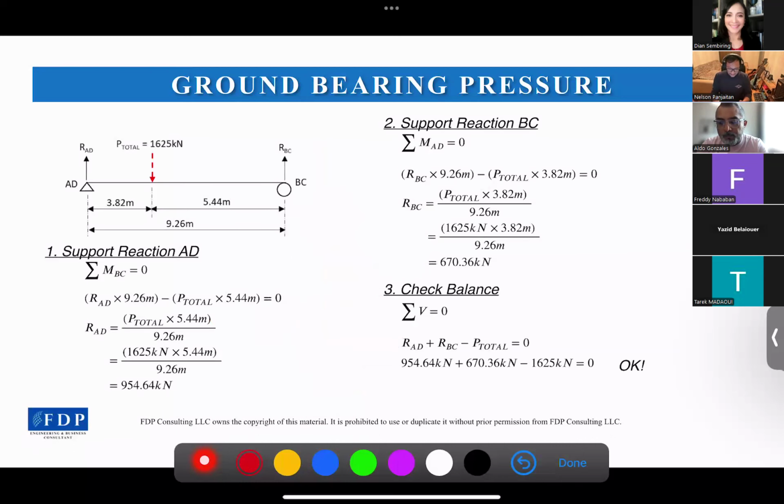Now we find out the reaction of each outrigger. I am assuming that this crane is rigid for this calculation, meaning that the deflection of the outrigger frame will be ignored, so that we can calculate this by using a determinate static structure analysis.